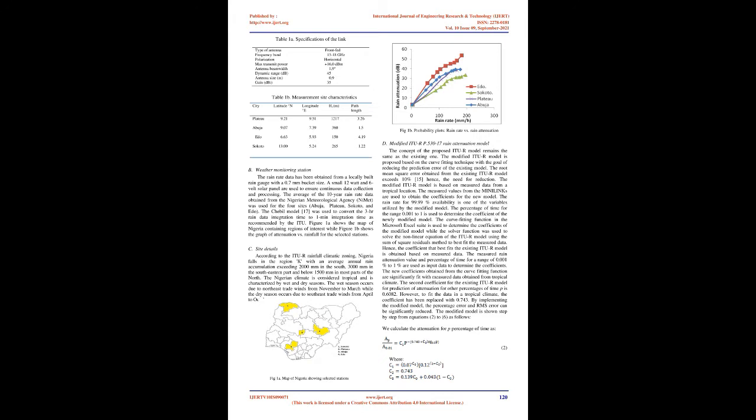The antenna is frequently sprayed with WD-40 spray to eliminate wet antenna effects. By doing this, interference from other hydrometeor sources becomes negligible. Specifications of the mini-link stations are shown in Table 1a, while the measurement site characteristics are shown in Table 1b. The signal monitoring device at the receiving stations, alongside a computer system, is used to monitor the signal strength at 1-minute intervals for rainy and clear sky conditions.